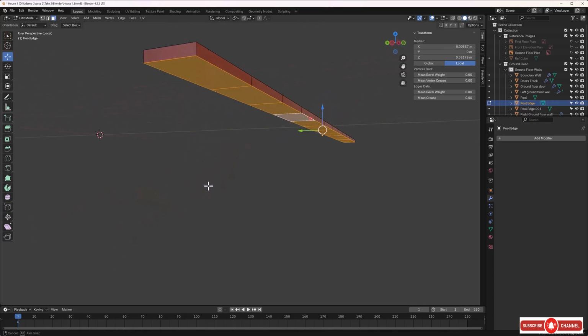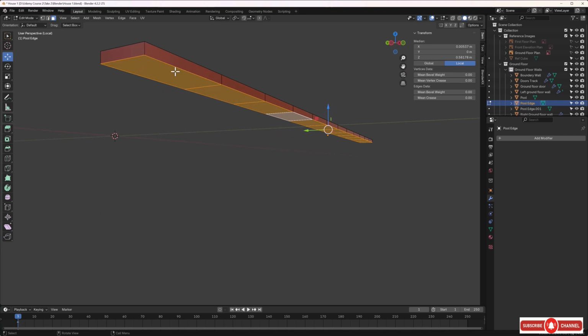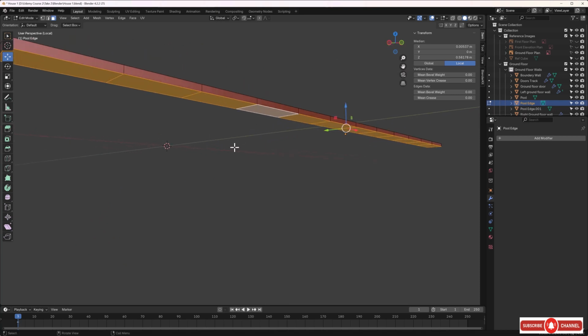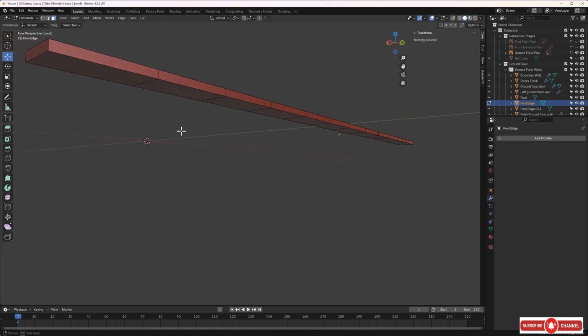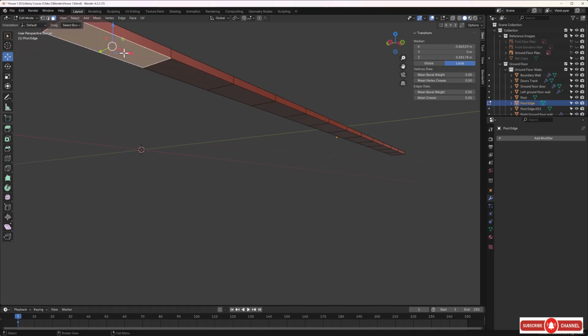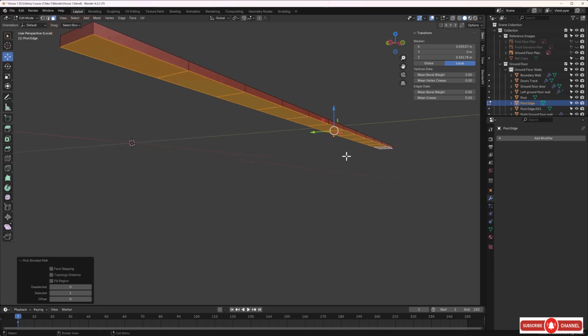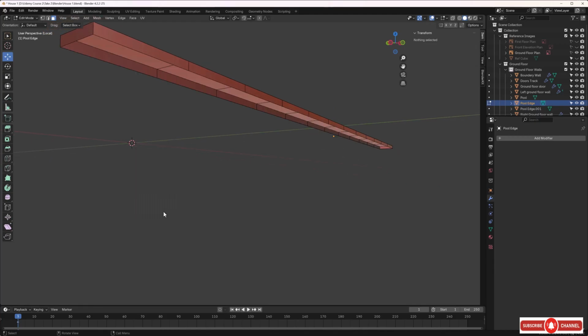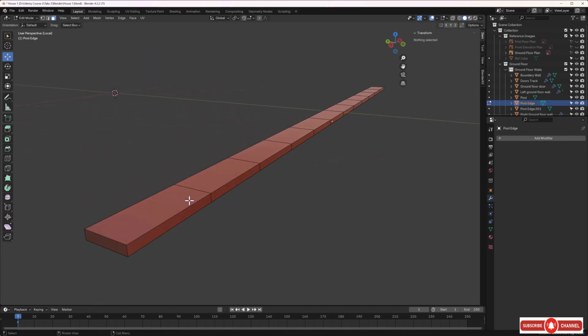Okay, yeah, we've got this bottom edge here selected, so that's what I want to do actually. So I'll just do it again to help you do the same. So I'll select this one, and I'm going to hold Control, go to the other end, and select this one. And that's selected all of them. Then I'm going to right click, and I'm going to delete those faces.